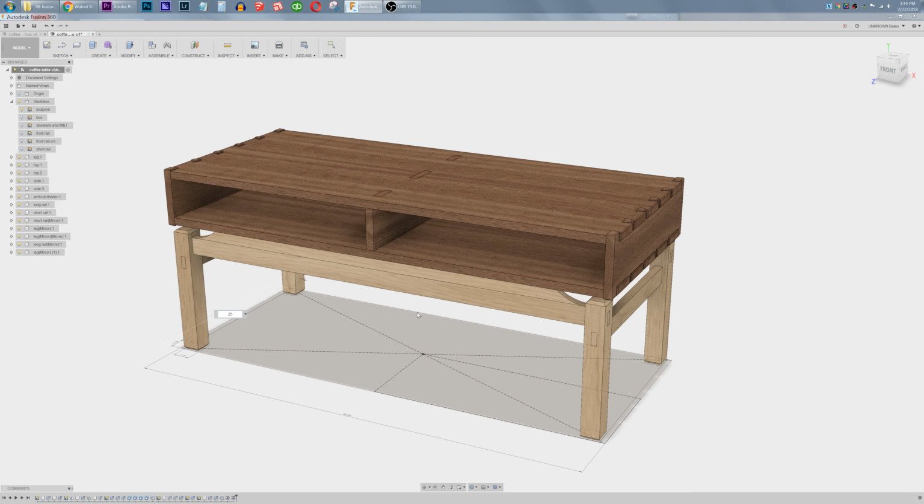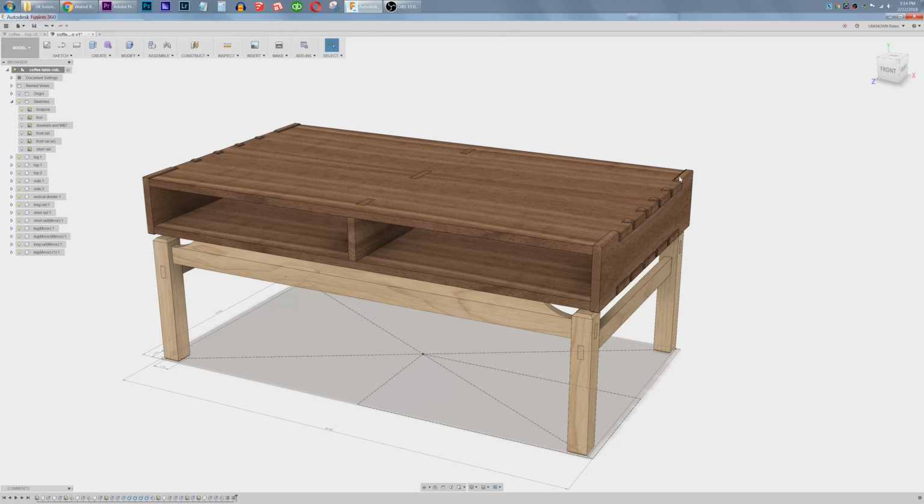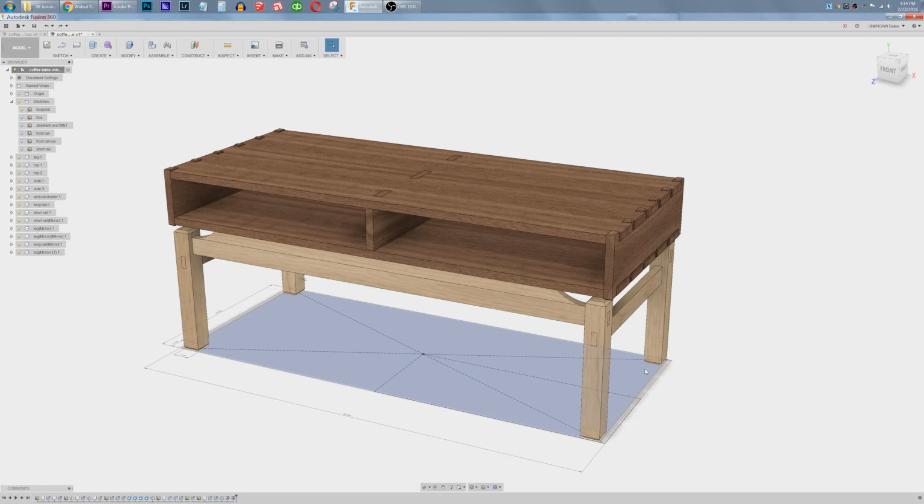And at that point, if it ever updates, yeah, these outside pins, I'll need to add another instance into that rectangular pattern if I want to keep that same 3 inches in width. Of course, you can set that 3 inches in width with a parameter to update and so on. But that is one of the very awesome benefits of parametric modeling.